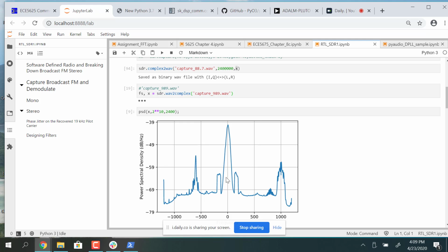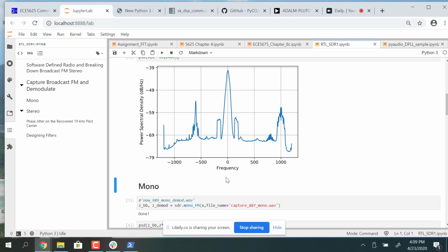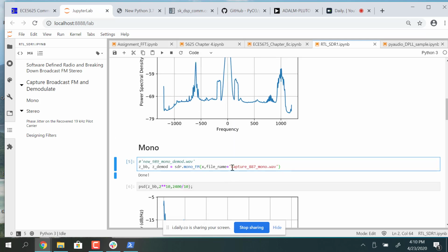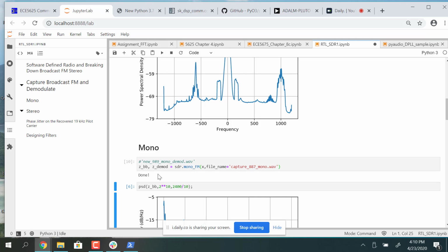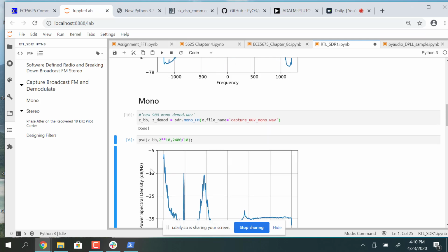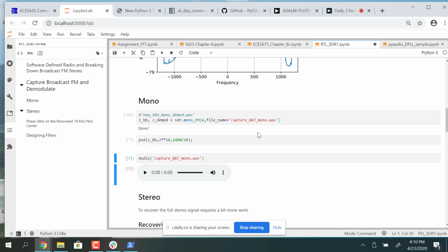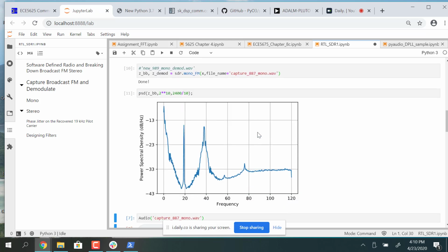So they can put multiple channels up in that digital part. But if I want to go a little bit further, I have a mono FM receiver that's in this package. So I'm just demodulating now my 5 seconds, and I can take it all the way down to audio I can listen to. But in the interim I can also look at the spectrum of the baseband after I've done some additional processing, things that you learn about in Lab 6. So let's take a look at that.